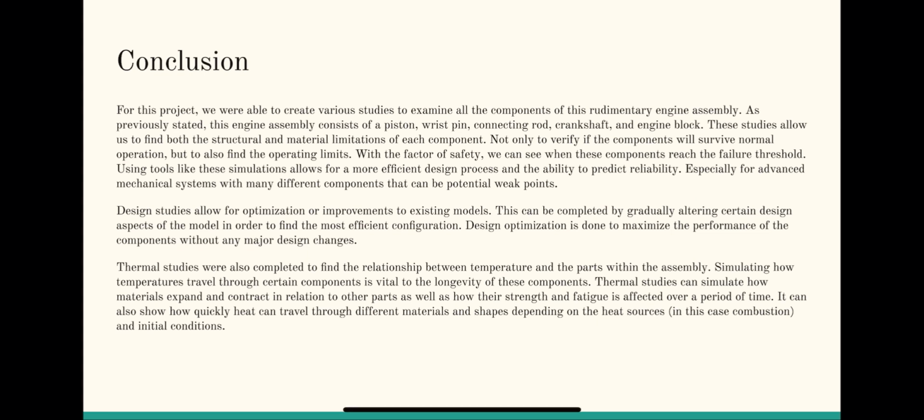For this project, we were able to create various studies to examine all the components of the rudimentary engine assembly. As previously stated, this engine assembly consists of a piston, wrist pin, connecting rod, crankshaft, and engine block. These studies allow us to find both the structural and material limitations for each component, not only to verify if the components will survive normal operation, but also to find the operating limits. With the factor of safety, we can see when these components reach the failure threshold.